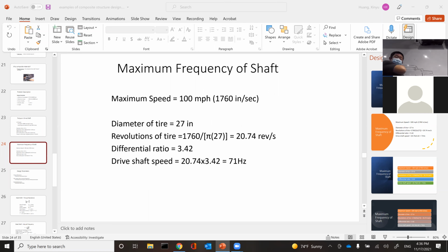There's a chance that when you speed up, your shaft RPM goes from 0 to 71 hertz, you'll hit 50 hertz somewhere in the middle, and then it'll cause some discomfort, the vibration. But if your shaft's lowest mode 1 vibration is 100 hertz, then you will never have this issue, because as you accelerate and speed up your car, your shaft starts spinning from 0 to 71, and you're still below the resonance. So you never go into resonance, which is desirable.